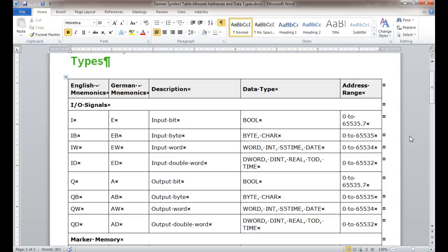They're saying, okay, I can come in and set a whole word, or I can set a single bit inside the word. So that's what we're doing when we clear out all our outputs. When we do our reset or our e-stop, we're just going out there and clearing out Q, right? So we're addressing a whole word, but then in our program we come back and address individual bits to actually control. But it's up to you to remember what's going on. Y'all understand? So it makes it a little more complicated.